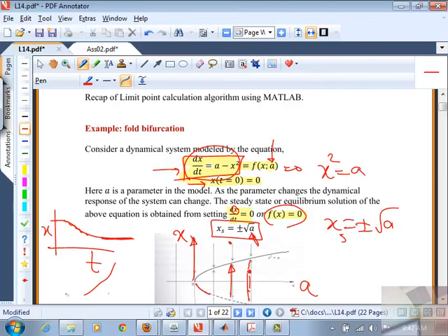But if you apply the Newton method, and this problem of course you won't because you can write the solution analytically, but if you have a problem like the CSTR, you are able to compute. There are solutions that are unstable in the CSTR problem. The middle branch is unstable, and I think I asked you to calculate the eigenvalues of those. You will find that the middle branch is unstable, but the Newton method will converge without any problem, converge quadratically. So the convergence of the Newton method is independent of that dynamical response. But if you use an ODE integrator, or if you do an experiment, you'll also not be able to get it.